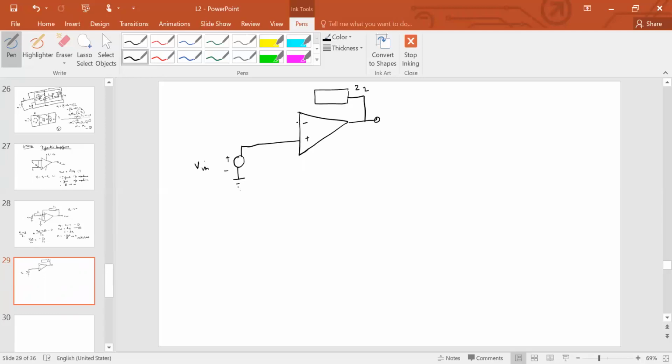This is Z2. It is basically divided here. And then you have this loop. And then I think this is Z1. Right? So this is the mode. Once again, as before, you can assume that V out is equal to nothing but A times VD. So what is VD now? This is A times V in minus, let's call this V1.